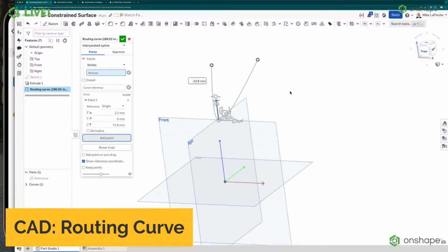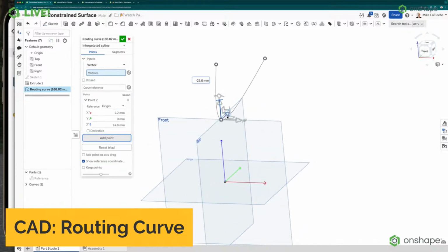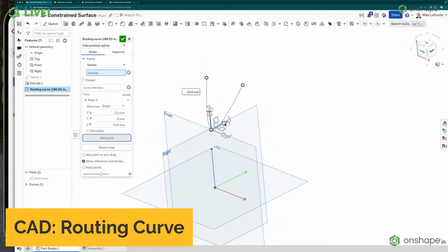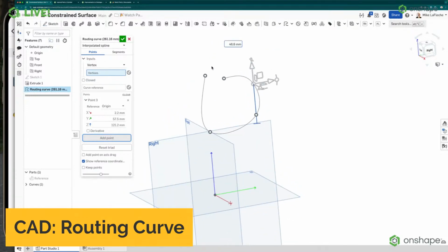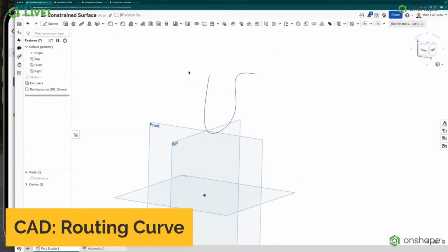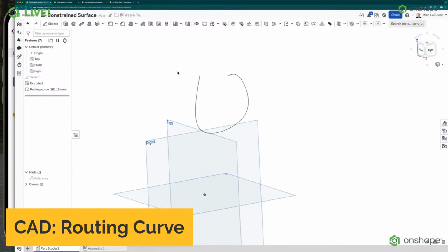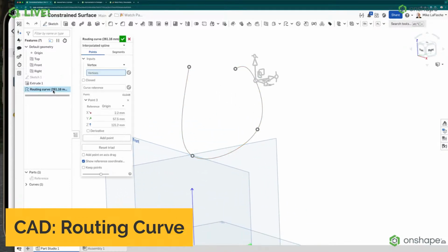Now we're getting a curve being pulled out like that. Of course, I can make it 3-dimensional. We've got this live manipulator. Now we're pushing out another point from here and moving that point up. Another point from that location, and now we can add another further point. So very quickly, we're able to get a 3D curve giving you the total length. You can change these positions at any time. If you don't want to go anywhere in X, we just move that back to 0 on point 3. You make that 50, make it 100.